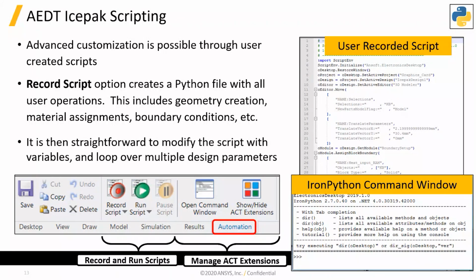That workflow can be fully automated. So right from importing, applying the material properties, boundary conditions, simulating it, exporting the report, all of this can be automated. And it saves you a lot of time when it comes to doing those repetitive tasks. By the way, these automation capabilities are not only for Icepak, these are for all the electronic suites, so we can utilize it effectively even if we are doing HFSS design, Maxwell design, Icepak design, all things available in the electromagnetic suite.